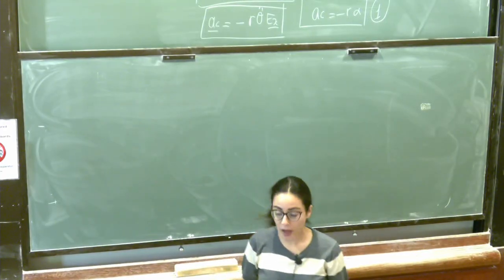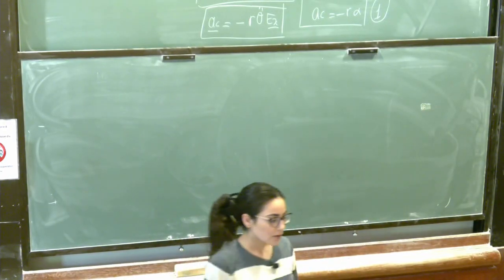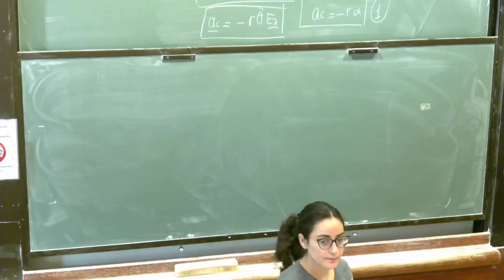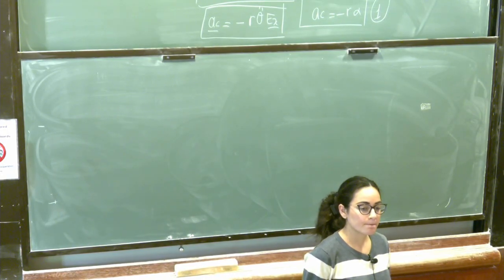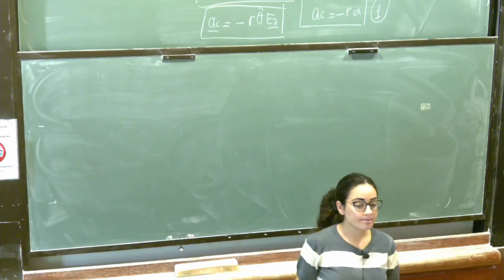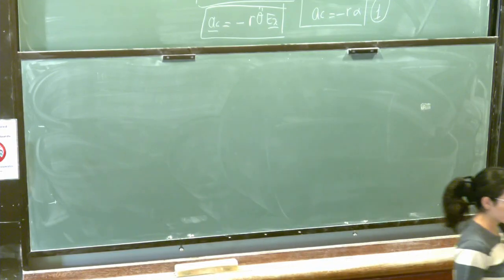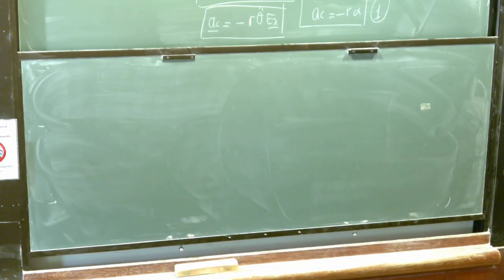So how do we find mu s so that the disk rolls without slipping? What are we going to do? If you find the friction force, then we know the normal force, and so we can use the inequality to find the minimum. Right.